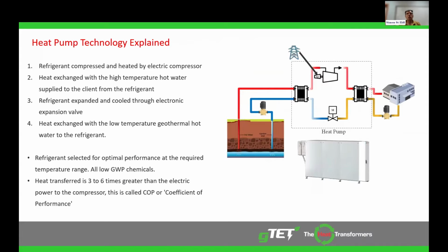I'm assuming everybody who's watching this knows how a heat pump works, but specifically in this case, we're taking the water and putting it into the evaporator. That makes it much better than an air source heat pump because the approach of the heat exchange is much closer, and you can lift it up much higher. Industrial processes generally use a small delta T on the hot side, maybe only 5 degrees. For that reason, we generally prefer to use low GWP HFO refrigerants. The CO2s of this world are really good at lifting an ambient water supply up and making it quite warm. But if you're dealing in a 120 or 100 degree space, then those refrigerants seem to work better.